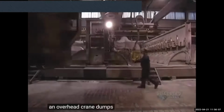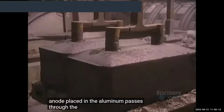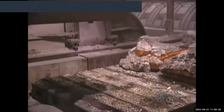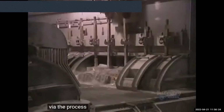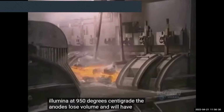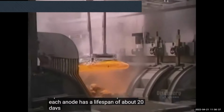An overhead crane dumps alumina into the pots. Then the electric current from the anode placed in the alumina passes through the alumina, which we see here right at the bottom of the pot. Via the process of reduction of the alumina at 950 degrees centigrade, the anodes lose volume and will have to be replaced. It's a continuous operation. Each anode has a lifespan of about 20 days.